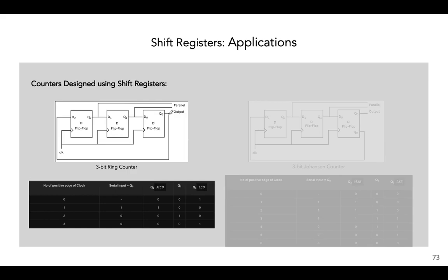And you can see that this output line is actually fed back into the register and it becomes the input here. So it moves from here to here, here to here, and here to here. Okay, so this is fed back into it. So this is now a loop. Another distinction is these parallel output lines. So we have taps here, and you can actually take the data out if you so desire.